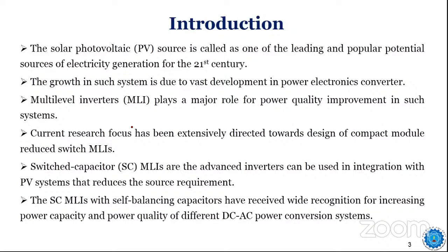That inverter converts your DC input to a compatible AC output, so that it can be fed to the grid. Here the inverter may be a 2-level or 3-level inverter, but multi-level inverters are emerging because they can improve the power quality, right? So when we develop a multi-level inverter, we will see the different types of inverter.